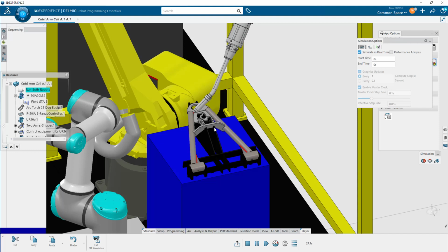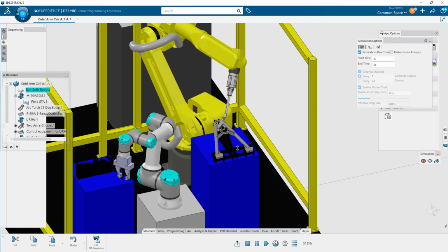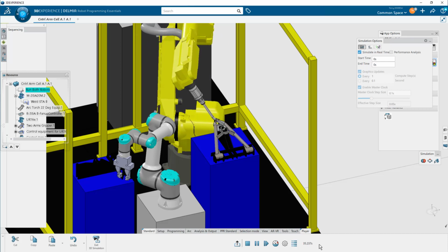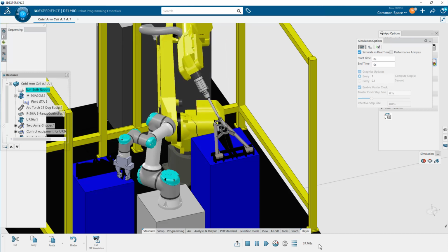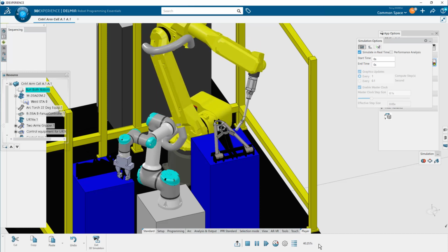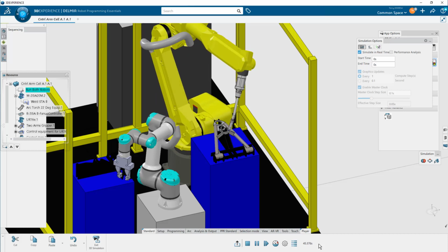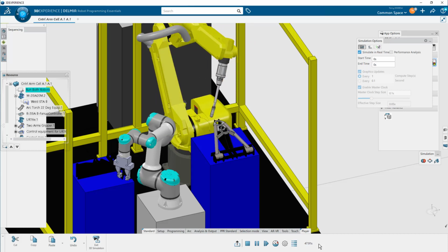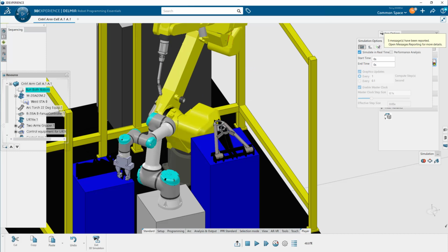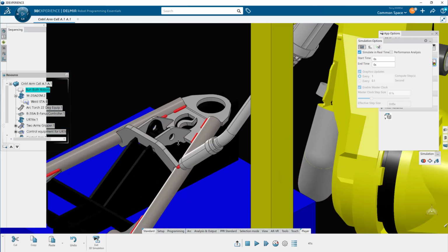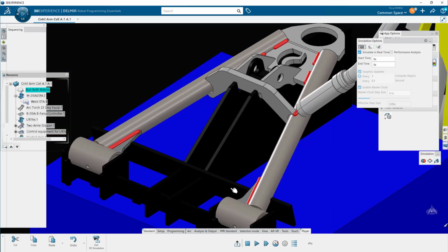And these arc profiles, you'll have a new arc profile according to whatever thicknesses you're welding, and they will all have different speeds attached to them, so that as you weld multiple types of steel, you'll have different weld profiles to apply. And these get applied at the download for the FANUC. When I hit the download button, these profiles will also be downloaded into that FANUC robot controller on the floor. And so the weld profiles, it's a good idea to have those in step with the weld schedules that they're using on the floor.